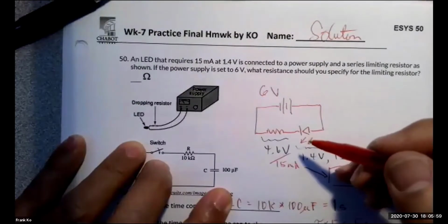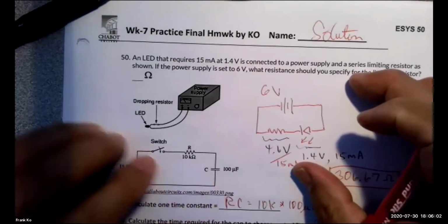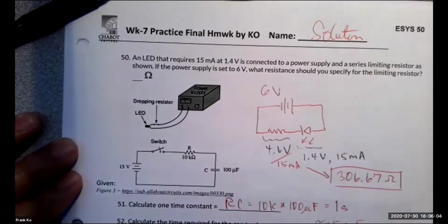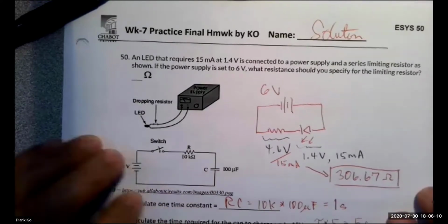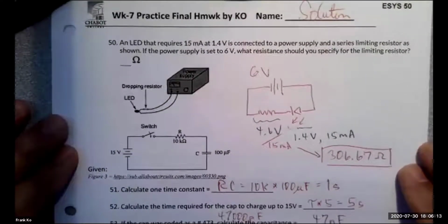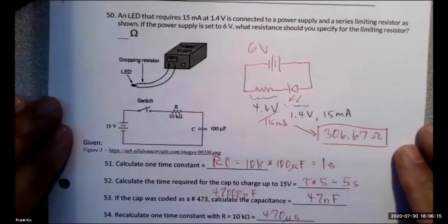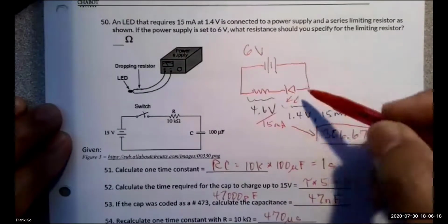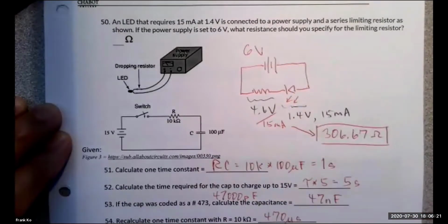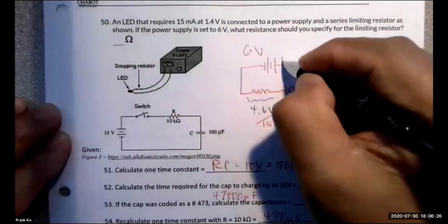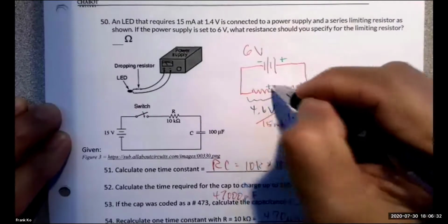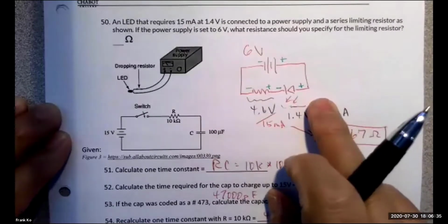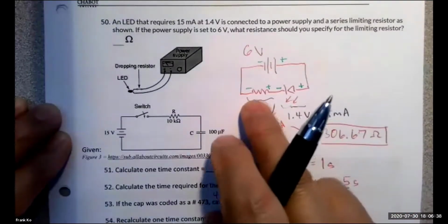Remember that when you built your LEDs in your circuit boards, if you wired the LED backwards, it would not light up. So here in this particular case, let me go ahead and speaker view so you can see this in greater detail. Is this a little larger where everybody can see better now? All right, so you draw the schematic, and you want to make sure that if this side of the source is positive and this is negative, then this side of the LED is positive, this side is negative. Those would be the polarities around the LED and the resistor.